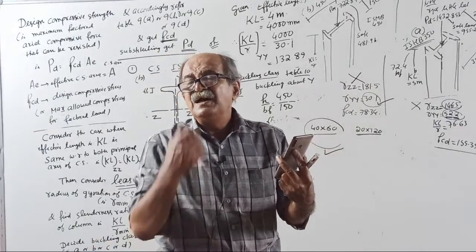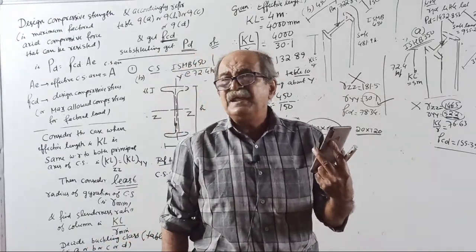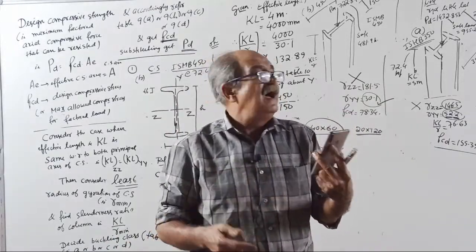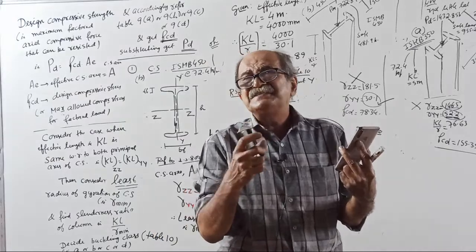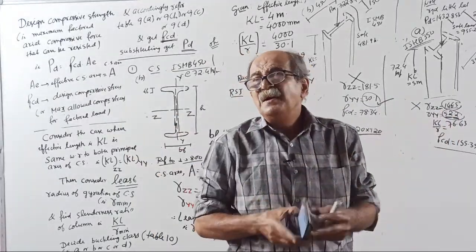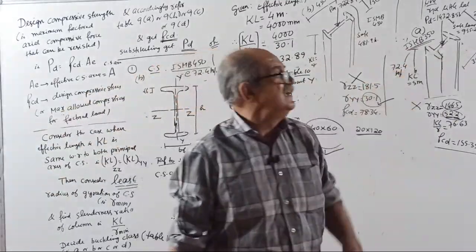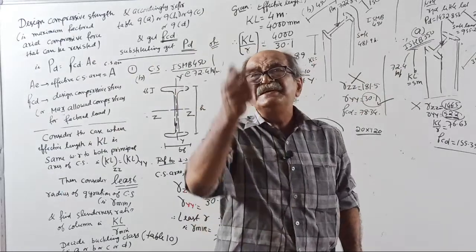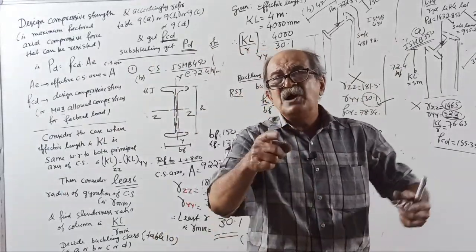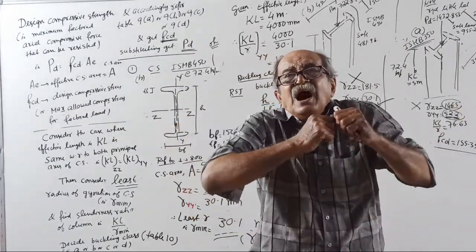First or second one? One column is 300 by 400. The other is 200 by 600. Lean and thin. First is better. Why? Buckling: for the first one, the weak dimension is 300. Second one, the weak dimension is 200. Clear now? That's why in case of a column, do you want a bulged section or a thin section?